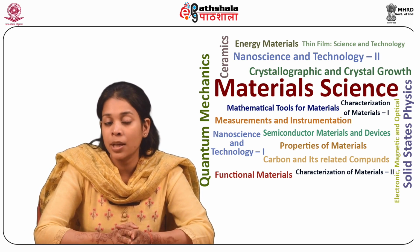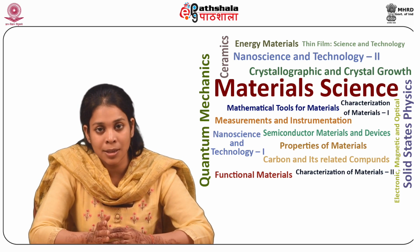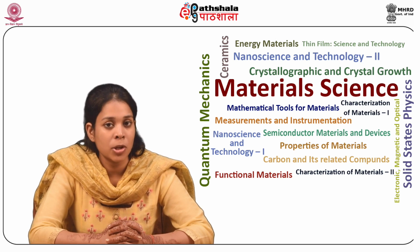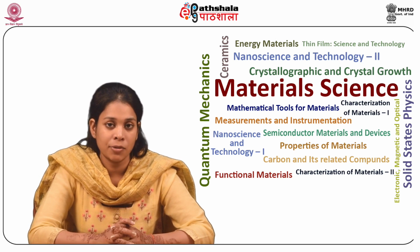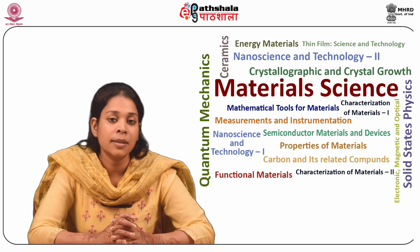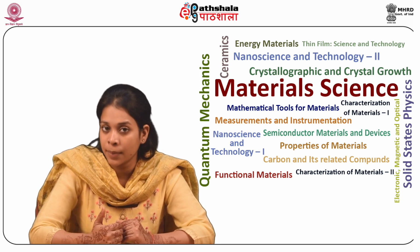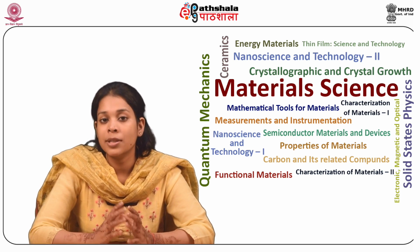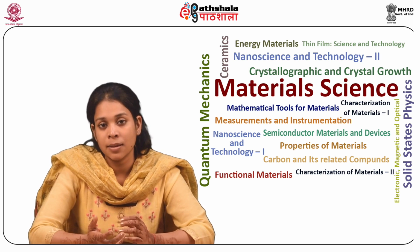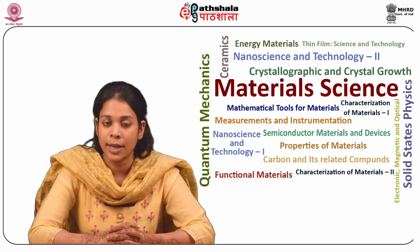The way of fabrication of the capacitive pressure sensor is different from that of the piezoelectric pressure sensor. In capacitive pressure sensors, a cavity is formed without any piezoelectric layer, and the cavity is surrounded by the top electrode and the bottom electrode. So the change in pressure results in a change in capacitance, resulting in the generation of voltage.